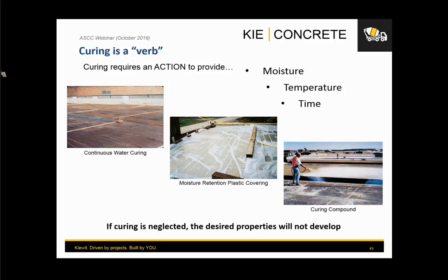And in some cases, for example, curing compounds can be pretty handy. They can be really helpful, but sometimes you need to recognize that curing compounds are not 100% impermeable. They breathe, and then the problem with curing compounds sometimes is that we go to the field and give the whole thing to somebody that doesn't know how to apply it. So then you have conditions where you say, okay, you're going to put a curing compound, and then you need to come on top and put water curing, right?